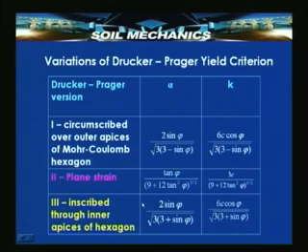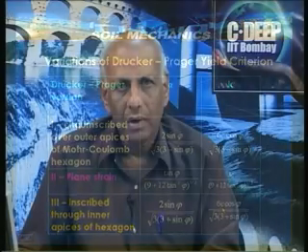And if on the other hand we use the inscribed circle which is within the hexagon, then alpha and k will become values shown in the last two columns of the table here. Depending upon whether we are analyzing a plane strain problem or whether we want an upper bound or a lower bound, we can choose the appropriate values of alpha and k in a typical analysis of say a tunnel or a slope using a finite element technique, for example.